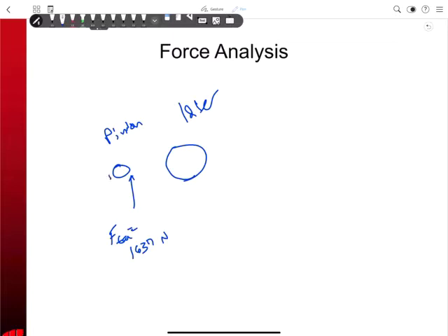And so if the tangential force on the pinion is resisting the motion, because that's driving, that means this thing must be rotating this way. And if that's rotating that way, this must be rotating this way, right, because the gears mesh here, and so the gear teeth move downward like that, which means on here there must be a force resisting or driving the motion.